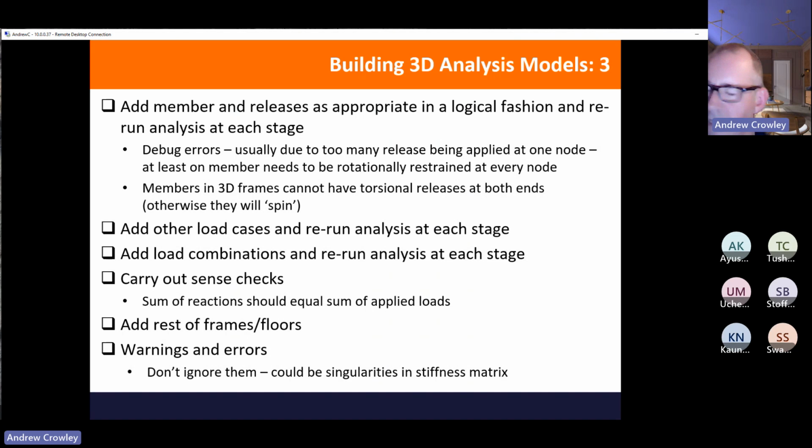In Multiframe, there is an option to click ignore tension-only members and then run the analysis. And suddenly you'll find your frame is much stiffer and your deflections are much lower. But that means your cables are taking compression, which is a mistake.